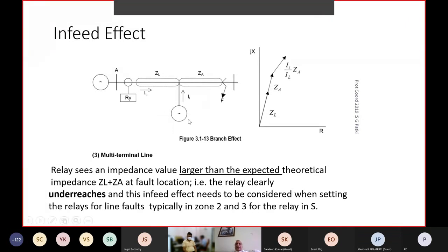But loop in, loop out and transition, normally if it is required to be done, it is actually a better practice to do loop in and loop out through separate circuit breaker. In short, you convert one long line into two short lines. So that is a better practice.